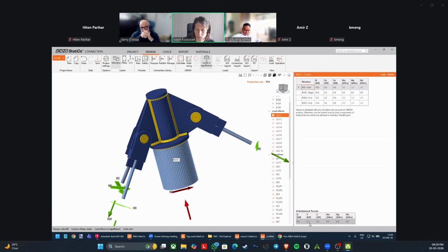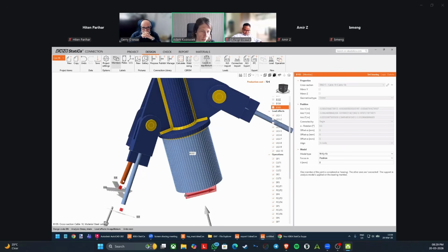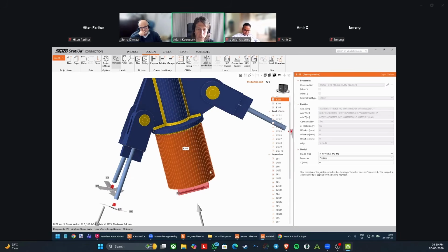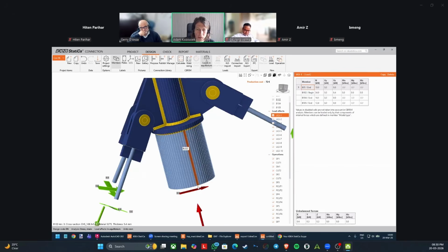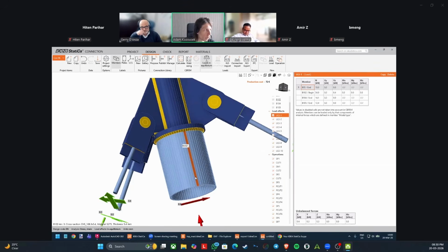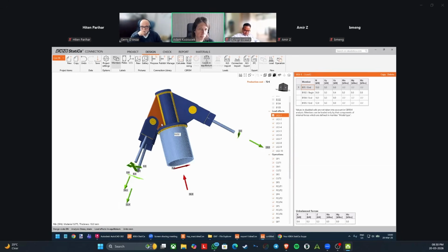But usually there are very small unbalanced forces, and it wouldn't be good to have a weak bearing member take these small unbalanced forces, because it can affect the results a little bit. If I have little unbalanced forces added here, the column takes everything because it's strong, so it doesn't affect the results of my analysis.